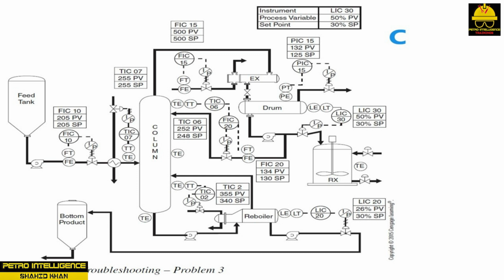Equipment or instrumentation failure can also damage the operation of a distillation column. Temperature, flows, pressure, level, and composition variables are closely tracked. Other problems include flooding, which will result in liquid accumulation in the tower, increased pressure drop, and poor separation of components. Other problems include downcomer flooding, jet flooding, local flooding, weeping, and overloading.